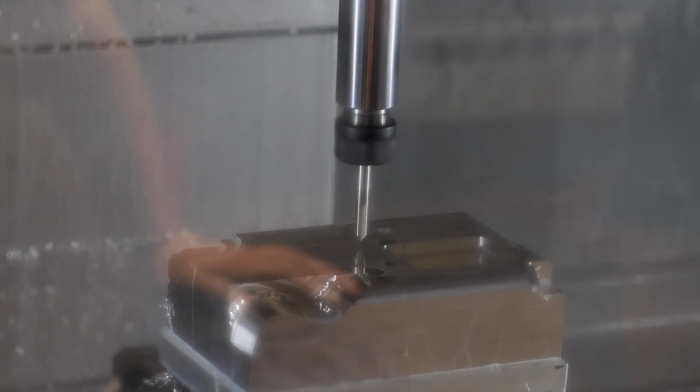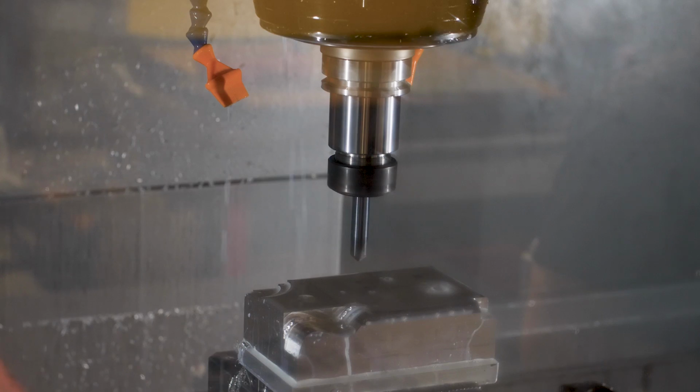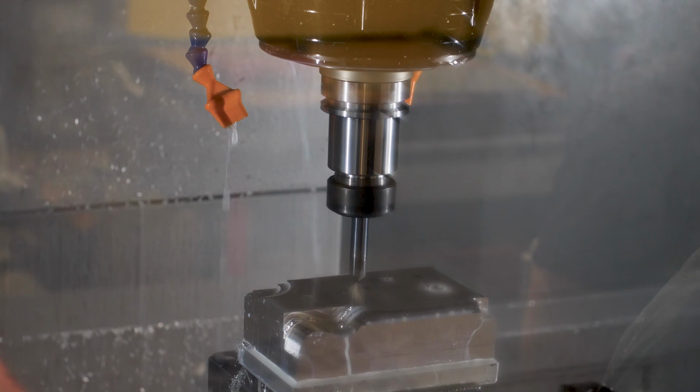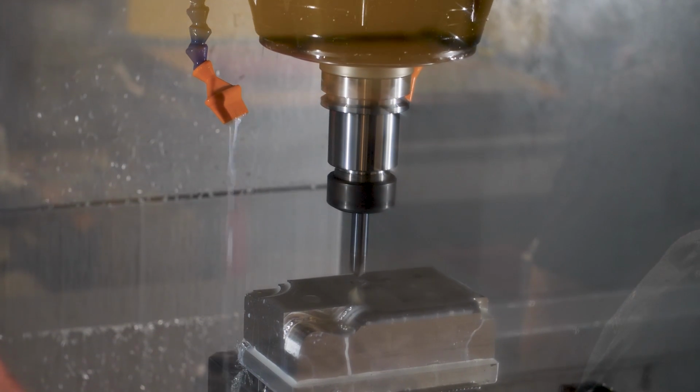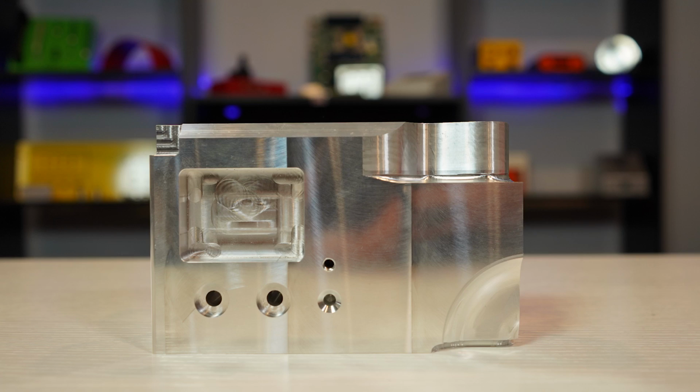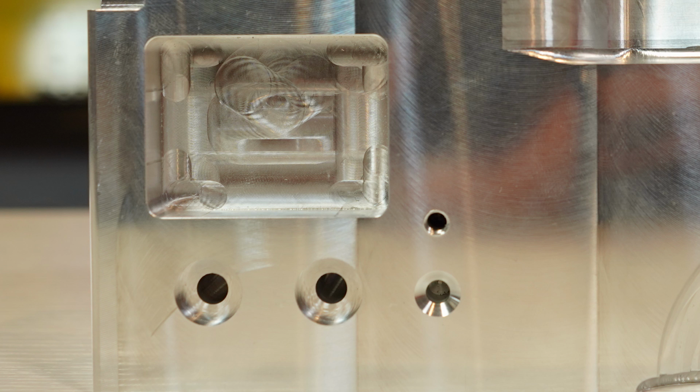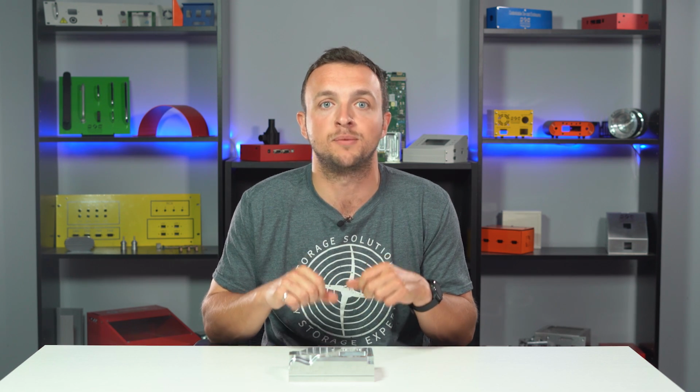A counterbore is a cylindrical, flat-bottomed hole that enlarges another coaxial hole. Counterbores are created using an end-mill tool type. A countersink is a conical hole that enlarges another coaxial hole. Countersinks are created using a countersinking or chamfering tool. Both counterbores and countersinks are used to prevent the head of a fastener from sitting proud on the surface of a part. By creating a counterbore or countersink, the fastener head sits below the surface of the part, avoiding any interference.